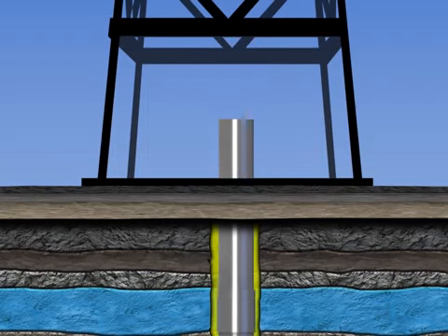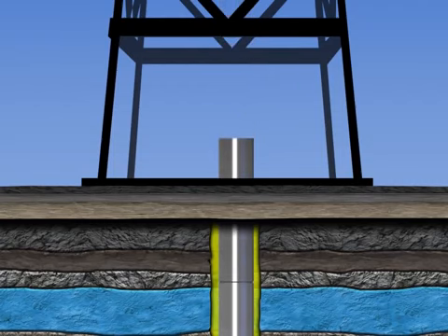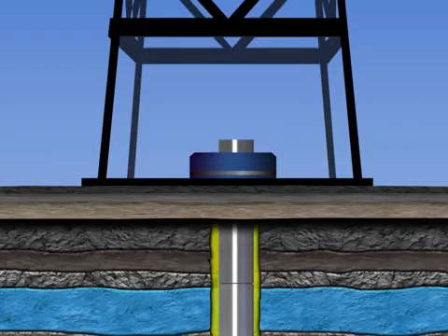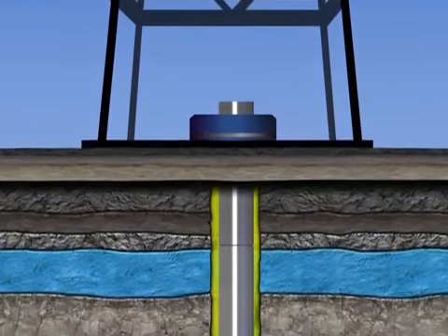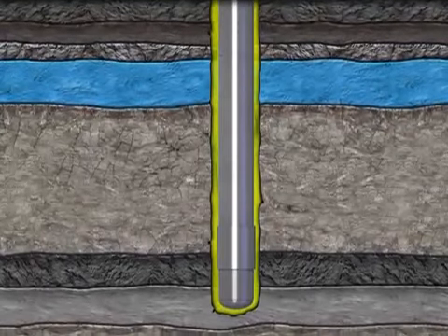The selection of grade of casing depends on several variables, including the size of the hole, the rugosity of the drilled hole, the expected pressure of the flowing hydrocarbons, the H2S content, as well as economic considerations. Once the entire weight of the casing string is solely suspended by the hangers, the casing is considered laid in place.